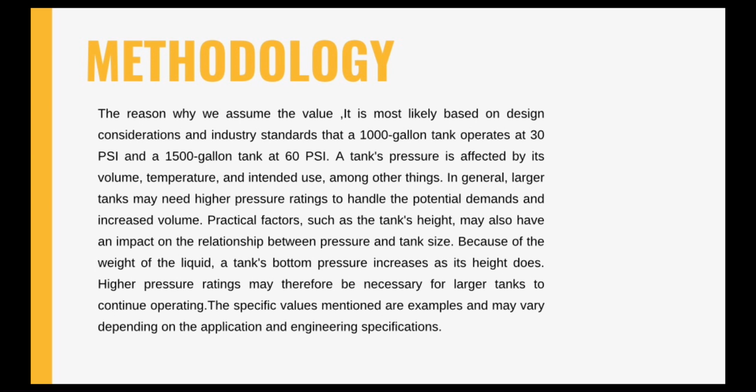Pressure is affected by its volume, temperature and intended use, among other things. In general, larger tanks may need higher pressure ratings to handle the increased demands and volume. Practical factors such as the tank height may also have an impact on the relationship between pressure and tank size. Because of the weight of the liquid, the tank bottom pressure increases as its height increases. Thus, a higher pressure rating may be necessary for larger tanks to continue operating. The specific values mentioned are examples and may vary depending on the application and engineering specification.